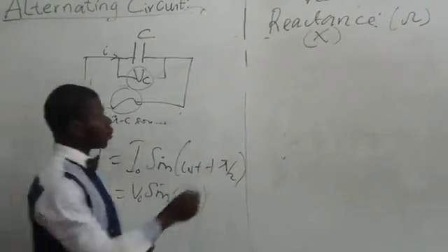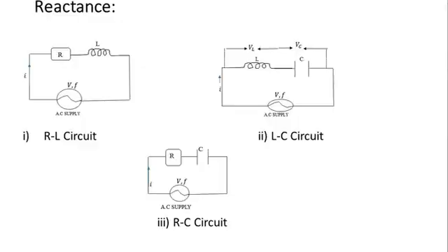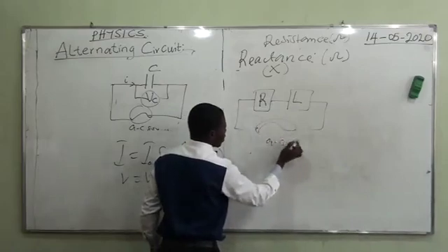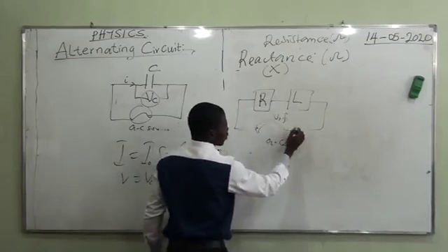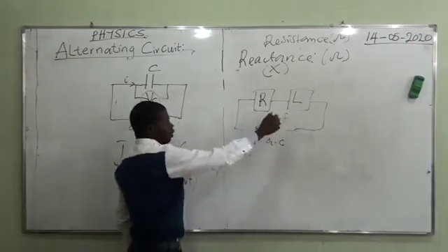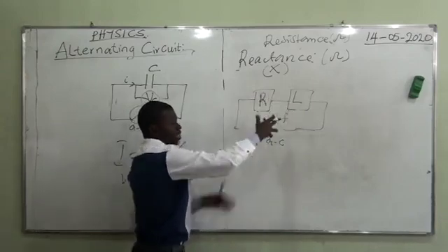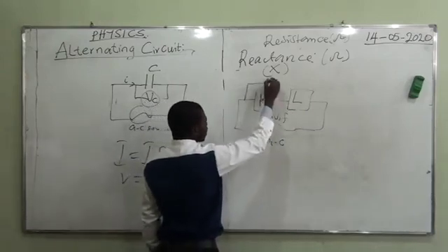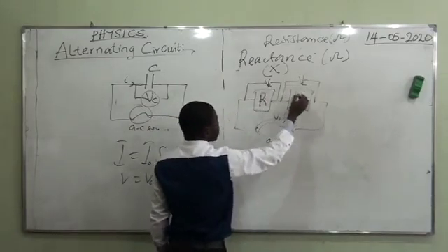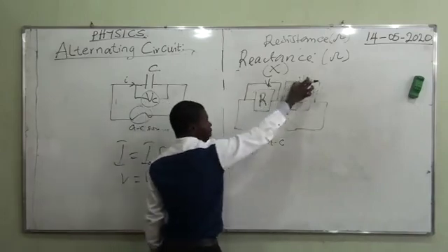So over there in the diagram, we begin with the first one. You have an RL circuit. What does that mean? You have a circuit that contains R and L. What does this mean? The resistor and inductor, all in series. Remember, the source is still the same. AC source, frequency, and wave. The wave of the, what's it called? Voltage. Alright? Move ahead. Remember from your Ohm's law, if you have two components in series, their voltage drop will be independent. So you have VR here and then VL there. What does it represent? Voltage drop across R, voltage drop across L.